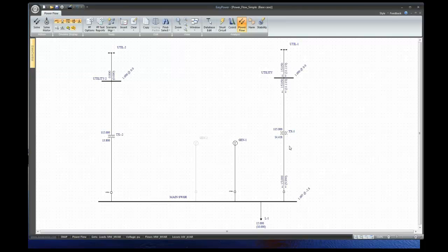Okay, so that's a way you can simulate the operation of the LTC. But remember, this is a steady state solution. So if I have some kind of impact loading, like a motor starting, I need to block the LTC because the LTC is slow. It's not going to respond during motor starting, or it's not going to respond quick enough to help you.